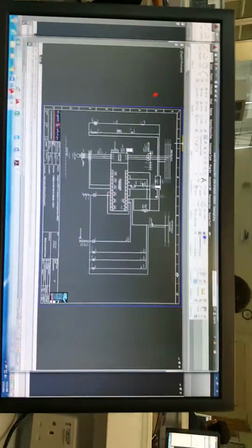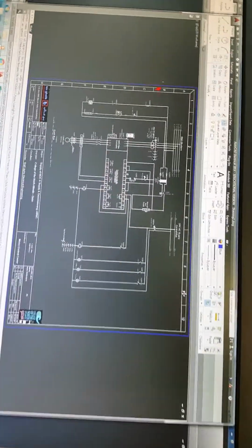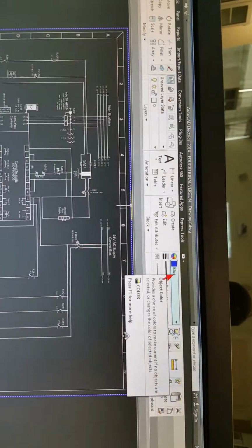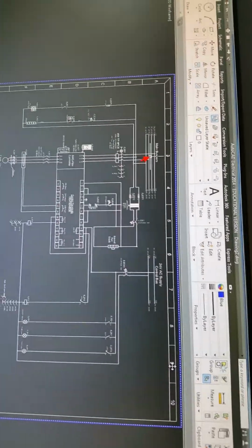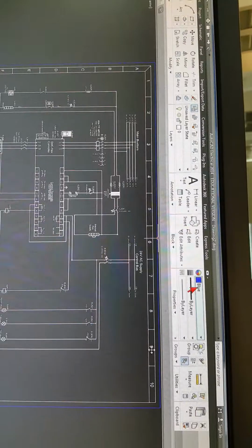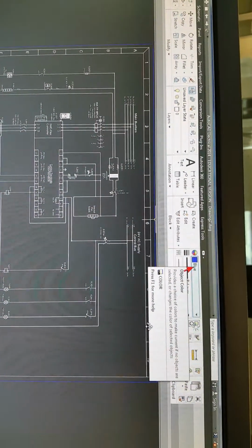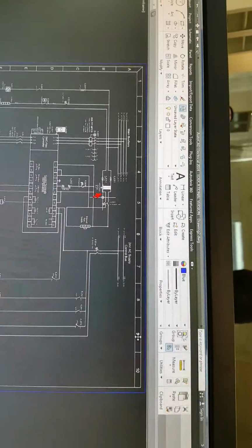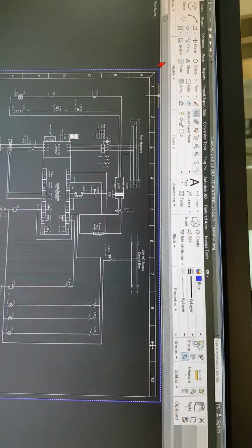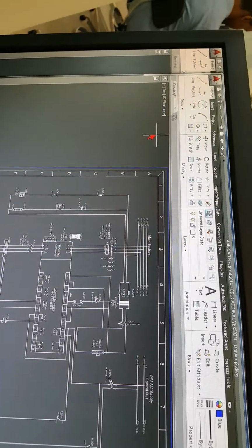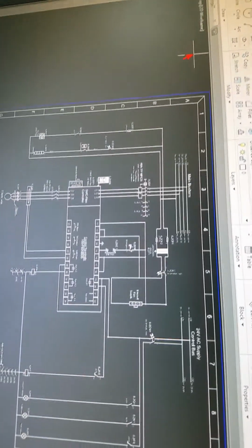See right now, if you see here on top, I'm forcing the layer to blue. Why? Because these are white lines. So it makes sense to have some other color to see where you have traced and where you have not. So I'm ready to go. We'll go line. The nice thing about this also is that your snaps work also on the PDF underlay.